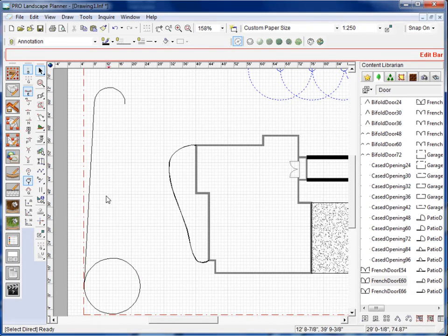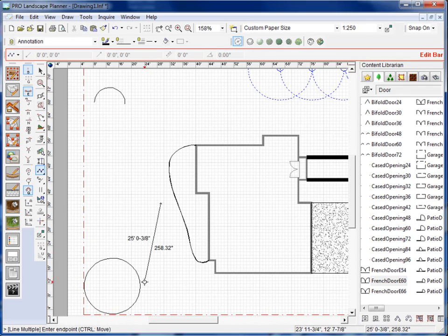The next one is called a quadrant snap. The quadrant snap is going to find the 4 quadrants of a circle. I can select my quadrant snap here, and I'm going to again use the line multiple. When I approach the 0 point, which is from the center point, the 0 point on that circle, I get a little indicator, and then I get another indicator at the 90-degree point, and another indicator at 180 and 270 degrees. That's relative to the center point of this circle.